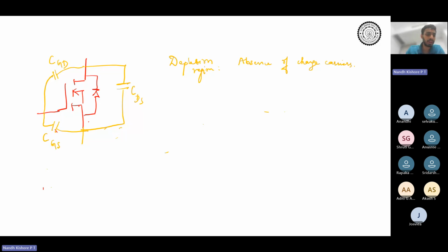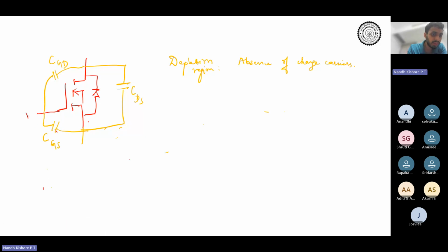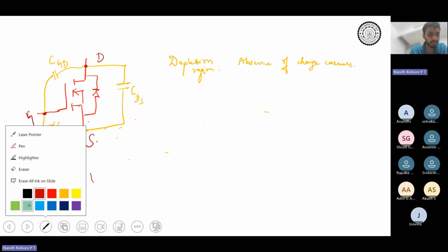So basically you have the gate to source capacitance, so you have gate, drain, and then source. Even though you have these three capacitances, generally, while we represent them, we call them CISS, the input side capacitance, COSS, the output side capacitance, and the reverse transfer capacitance, CRSS. So how do we find that out? We will go back to first year Thevenin's theorem, that will help.